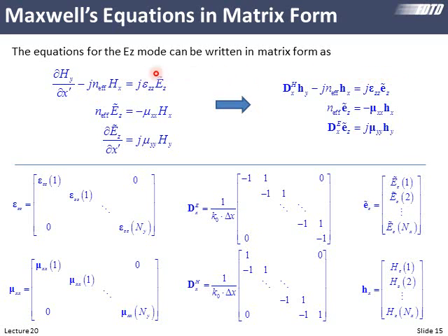Now, the permittivity and permeability, we are doing a point-by-point multiplication here. So the way we store these, and in a way it's similar to a column vector, we have these distributed throughout a grid. We can reshape that to a column vector. However, we will stick that column vector down the diagonal of an otherwise zero matrix. It's zeros out here and zeros out here.